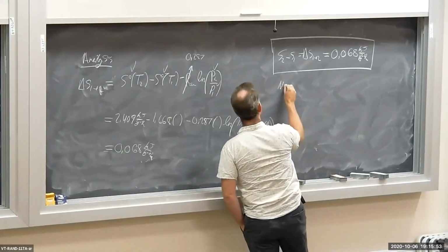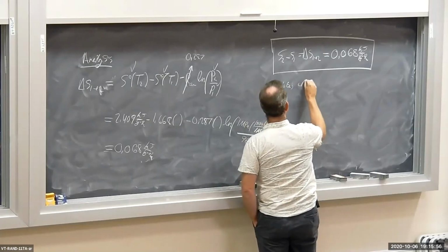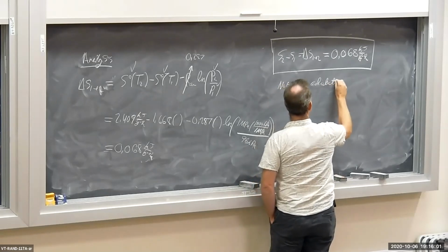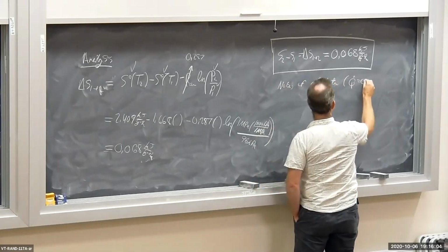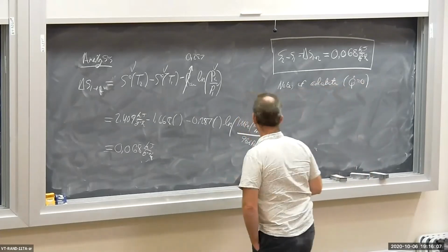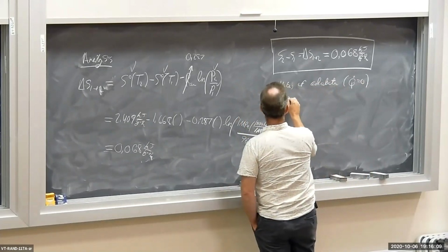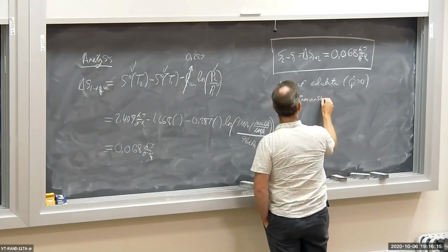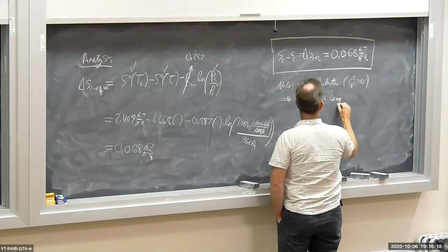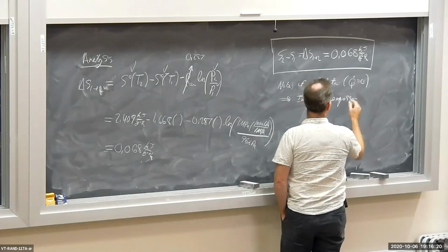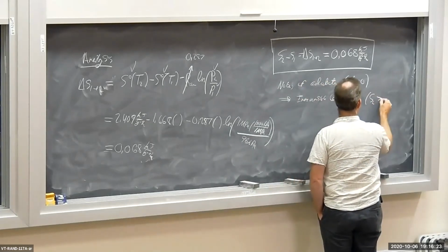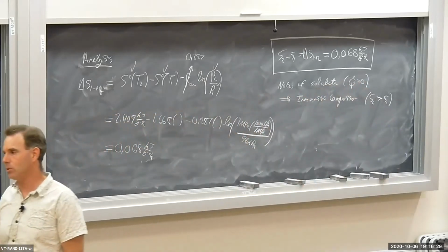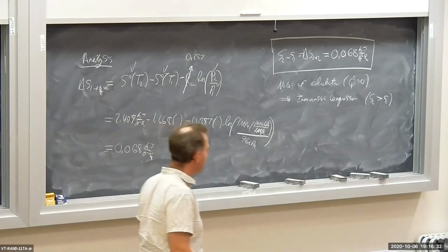Note, if adiabatic, in other words Q dot is equal to 0, no heat transfer, then this is definitely an irreversible compressor. Why? Because S2 is greater than S1, okay? We'll talk about this a little bit more when we get into open systems in the next lecture.